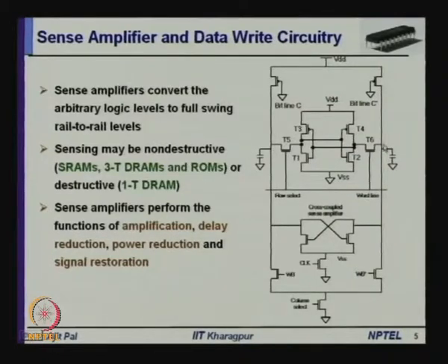On the other hand, when this is 0, this 0 will turn this transistor off. So, one is supporting the other. You are applying both the signals, and very quickly, because of regenerative feedback, the change occurs and you get 1 and 0 at the output of this inverter and the output of this inverter. Then the word line signal is withdrawn, write signals are withdrawn, and information will remain in this cell as long as VDD is maintained.